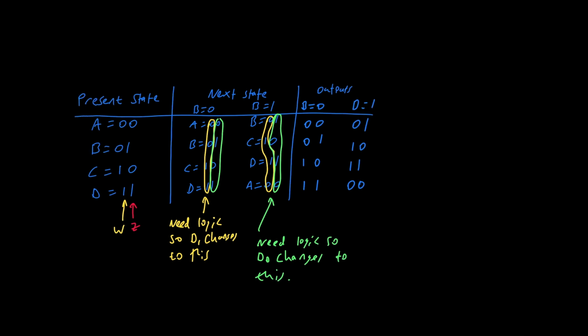The next state transition table will help with further analysis. Here, we have assigned state codes so that the states represent the numbers that also need outputting. You can see how we have the necessary transitions from the present state in the first column to the next state in the second column when B is 0 and 1 respectively. We also require 2 bits for the output to represent each number output. Although we won't go further into what happens to the outputs, further logic would be required to connect it to the displays.